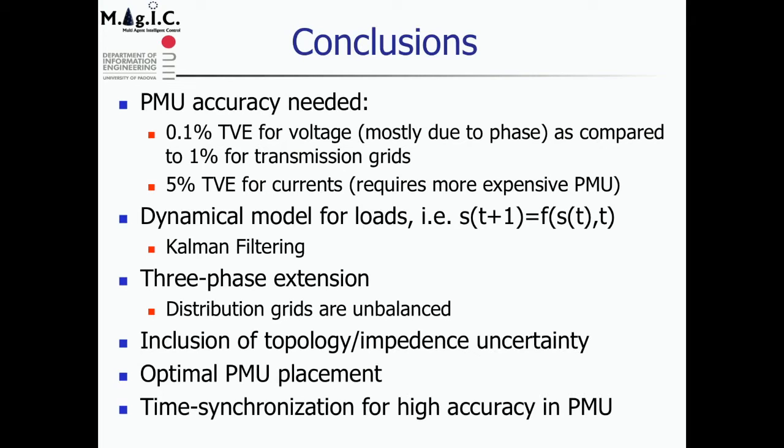Other important problems regard optimal PMU placement, because those are expensive, so I want to use as few as possible. And finally, in order to get very good performance, I need to have a very fine time synchronization in PMUs.